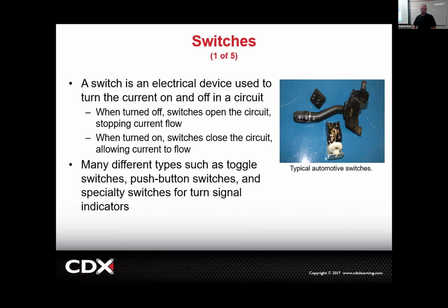So what's kind of annoying in automotive is, let's say that you had a problem with the windshield washer pump and you press this and you diagnose that this part of the switch is no good. You've got to replace this whole entire switch. It's hard to diagnose these because it's not just like 2 wires. There's 20 wires going into this thing. So how are you going to know which 2 wires control the washer pump? You're all over the wiring diagram. You're like, it's this terminal and this terminal.